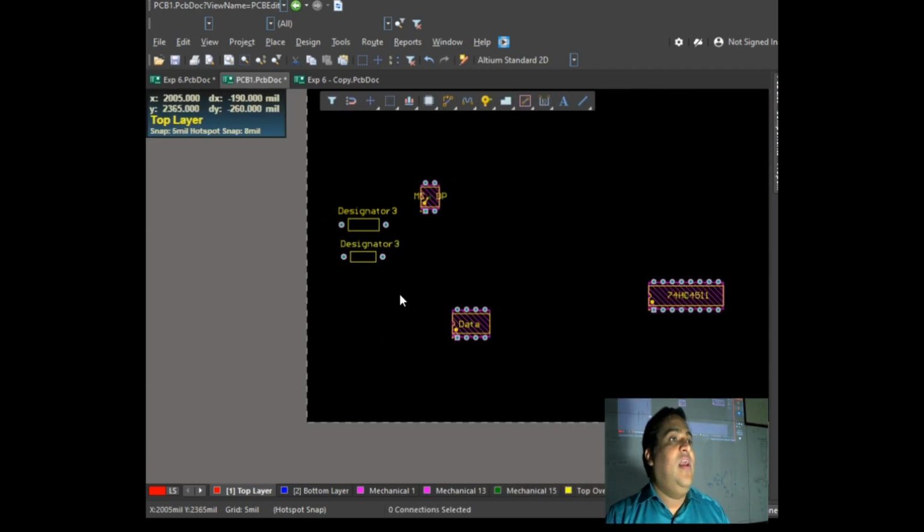So if you want a smaller footprint, whenever you place this resistor over here, you can see the legs coming out. If you don't want those legs, then certainly you can use this designator 3. Then the legs will all be inside the hole and you can cut them at the back when you are soldering it. But if you want a little longer patch, then you can use this designator 3, the 10 cross whatever that size was.